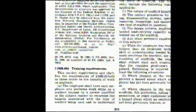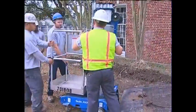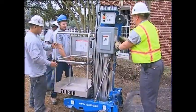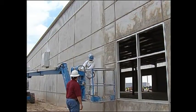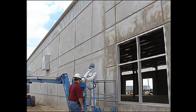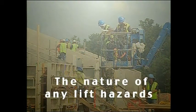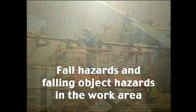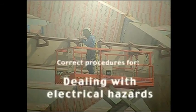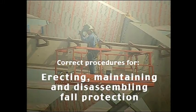OSHA requires training for aerial lifts and scissor lifts according to CFR 1926.454. Employers should train operators, employees that work on aerial lifts, and other personnel as necessary. It is important never to attempt to use a lift without being properly trained on its use and its shortcomings. Training should include the nature of any lift hazards, electrical hazards, fall hazards and falling object hazards in the work area, the correct procedures for dealing with electrical hazards and for erecting, maintaining, and disassembling the fall protection systems and